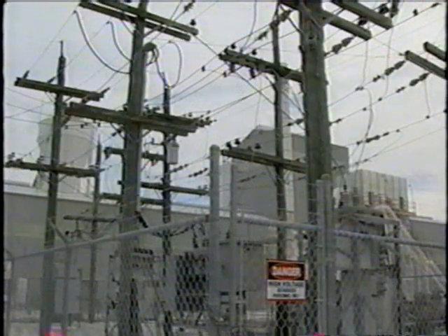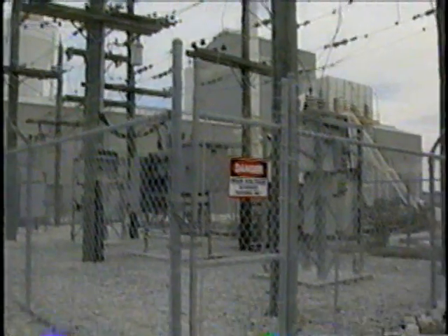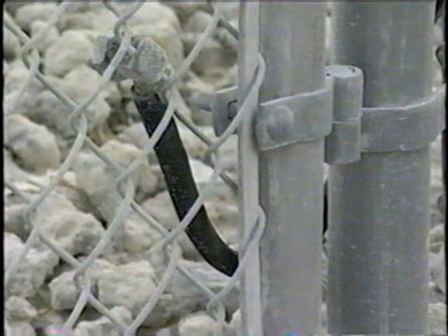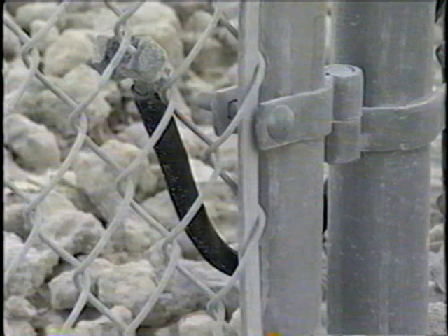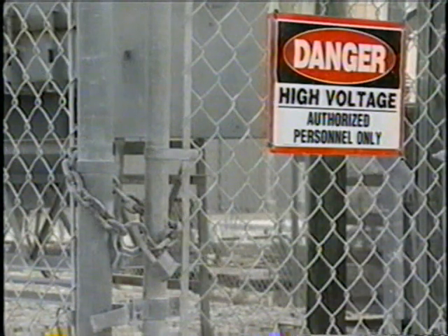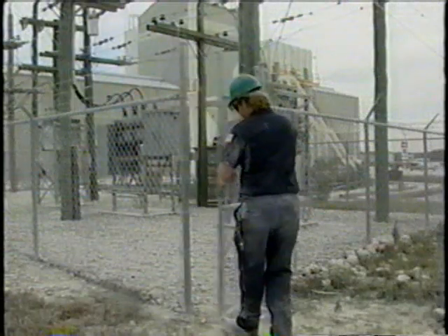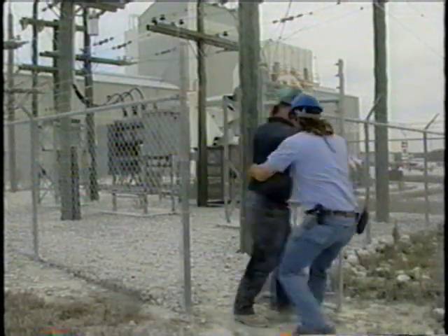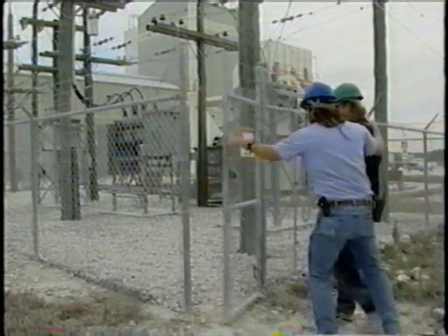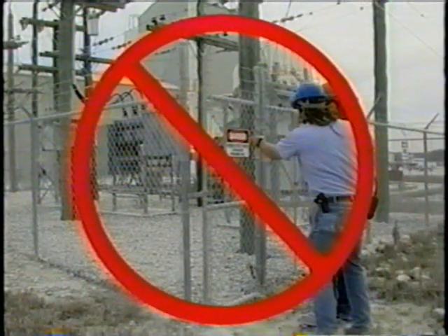High voltage areas and electrical substations must be locked, grounded or bonded, and free of vegetation. High voltage signs should be placed around the fenced enclosure. Also, unless you are specifically trained and certified to work in these areas, under no circumstances should you attempt inspection or repair.